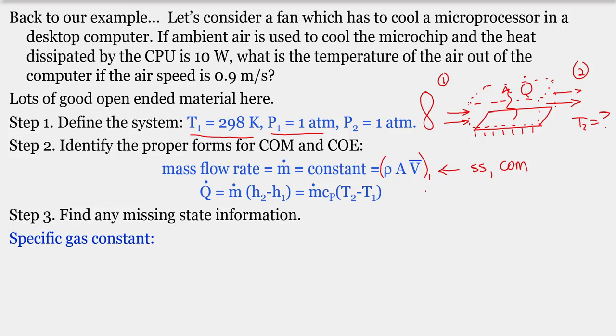Now we were looking for the temperature, and so we know that we're not going to get any temperature information from the mass flow rate of the exit. So instead, we're going to look to the conservation of energy to tell us the temperature of the system. And we solved, again, using a steady state assumption. We assumed that there was no work transfer in the system, which is a good assumption. There's no electrical energy, there's no shafts, no expansion or compression. And again, those are all assumptions that are linked to our definition of the system.